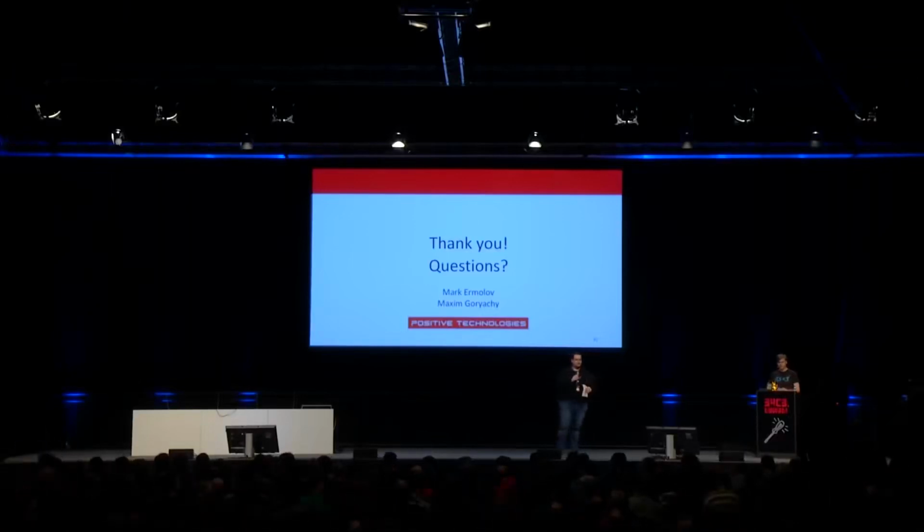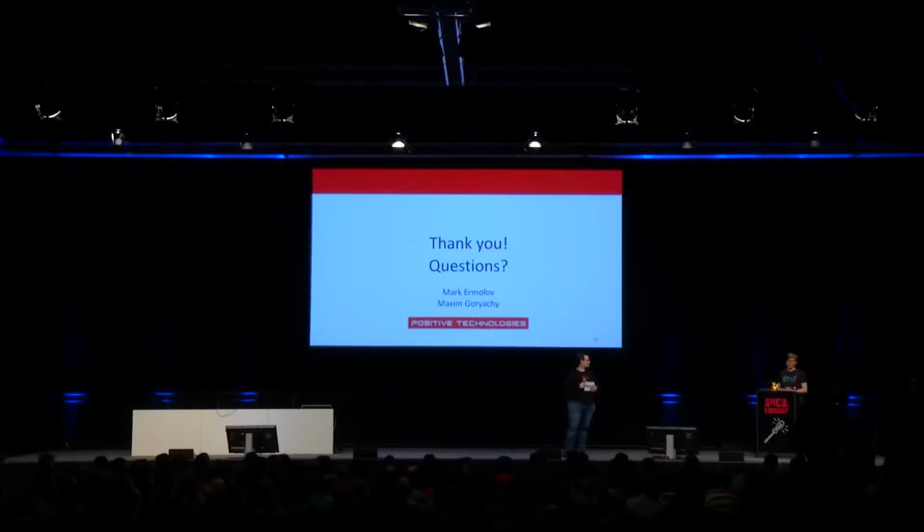So already here at microphone number 1. Okay, so you mentioned that you dumped the ROM. And previously, there were some firmwares with ROM bypass available. Did you compare the dumped ROM against ROM bypass? Yeah. And is it the same? No. We found some difference, but it relates to the fact that the ME bypass code starts in protected mode, but the real ROM starts in real mode. Okay, so otherwise it's functionally almost the same.